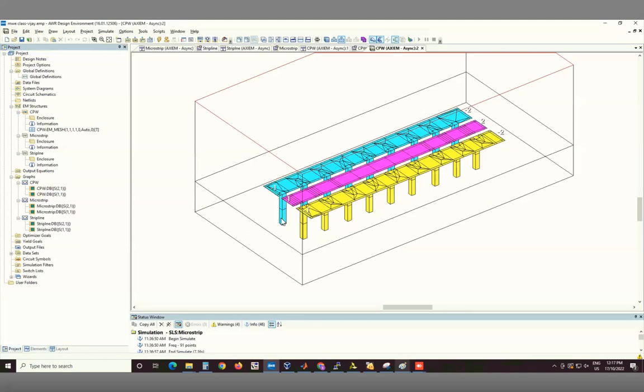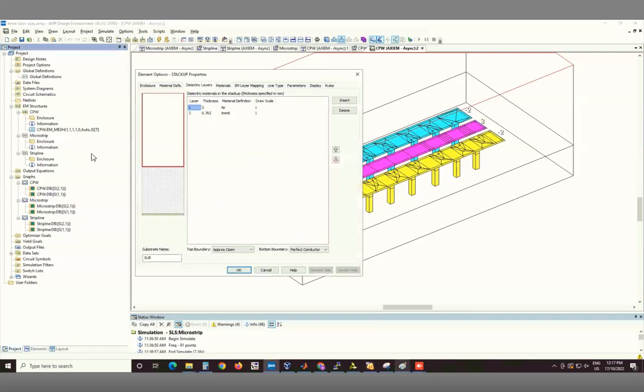If you want to simulate that here, all you have to do is change the enclosure slightly and create a structure going upwards. For that, we have to play a trick here, because right now there is no top layer. I cannot draw anything on the surface. So I'm going to insert an extra layer of air. It's basically a dummy layer. I'm breaking up that air, just like in a strip line, where you needed two layers to define a metal in between. To keep everything else the same, I'm going to make this 1 millimeter each, so that the total thickness remains the same.